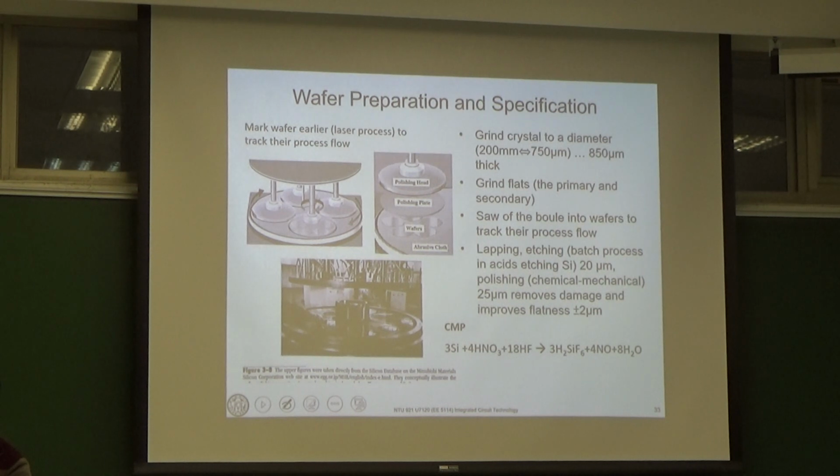This is the wafer that we polish to make it like a mirror, and we also need to polish it to a certain thickness, because for different process purposes you may specify, okay, I want 750 micron. That's the thickness, or like 1 millimeter thickness.